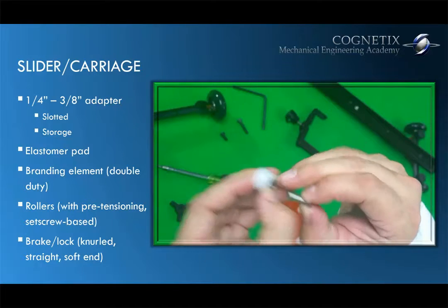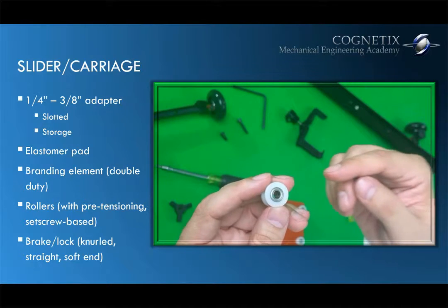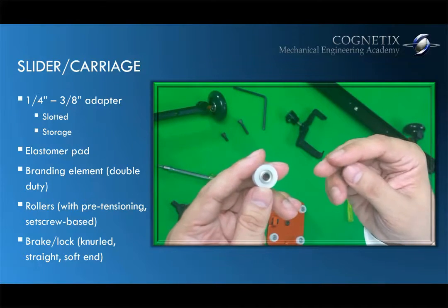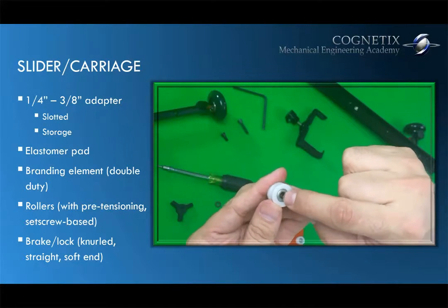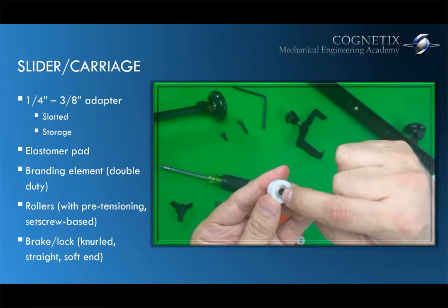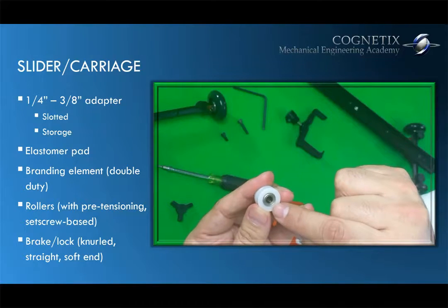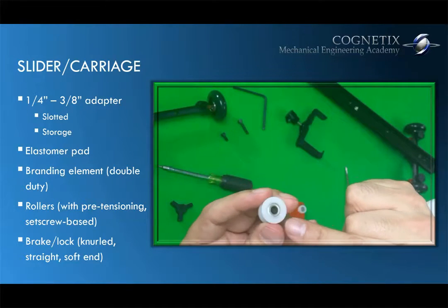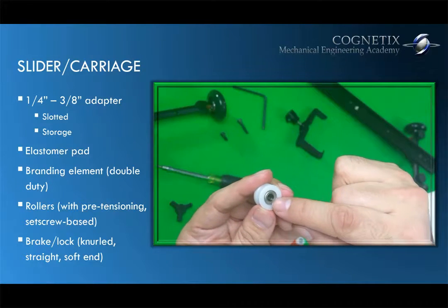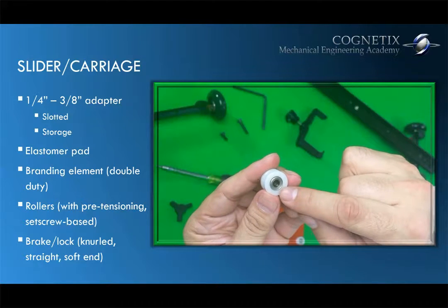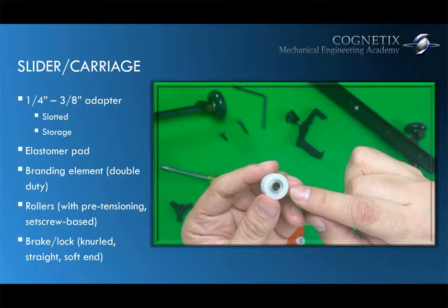Now, before I show you the other part, remember when we talked about bearings, there's an inner race and an outer race when we're talking about ball bearings. Inner race, of course, is the smaller diameter race. It's a sleeve, cylindrical in shape, that you can see turns. And then the outer race is the largest possible diameter in contact with this probably nylon roller. And in between the inner race and the outer race, we have the ball bearings. So a very, very low friction, efficient way of producing rotary motion.